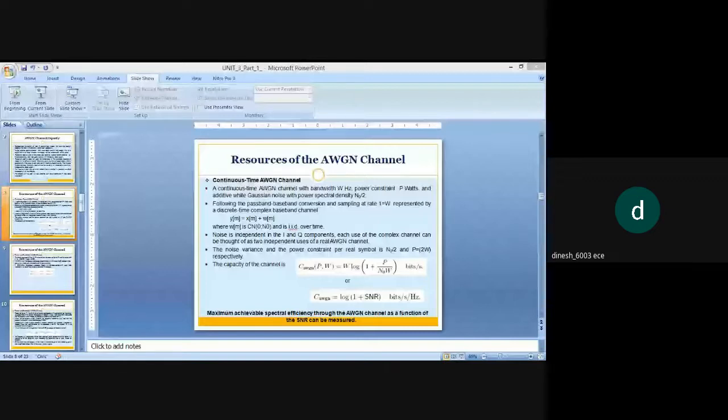So for different channel information assumptions, different definitions of channel capacity are given, depending on whether the capacity characterizes the maximum rate taken as an average over all fading states, or the maximum constant rate that can be maintained in all fading states, with or without the consideration of probability of outage.